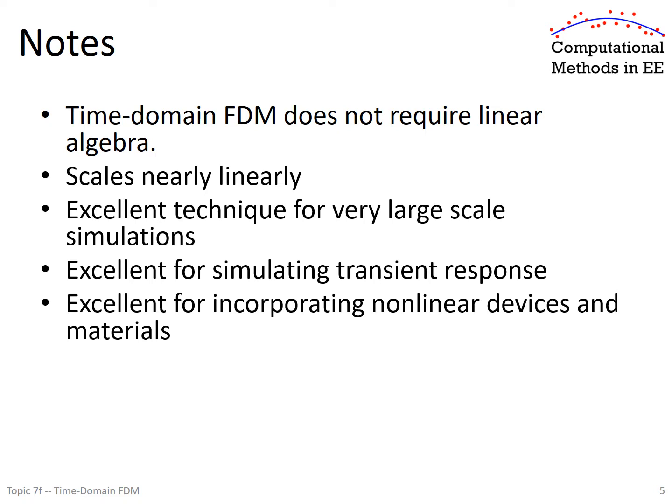If we have nonlinear properties or materials such as diodes or just nonlinear materials, that can be done in the frequency domain, but it's very easy and inherently simple in the time domain. So for nonlinear properties, seek a time domain method.